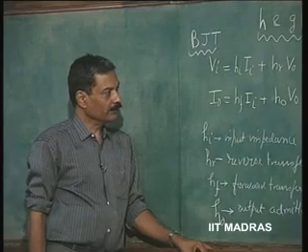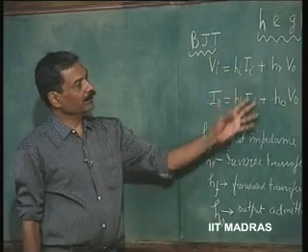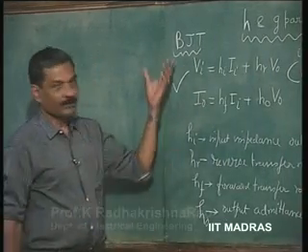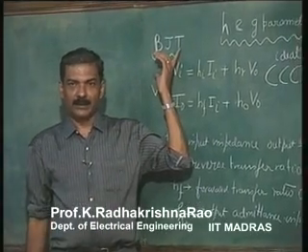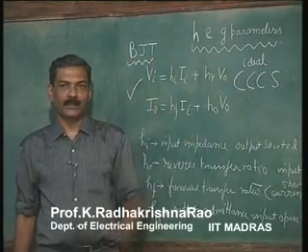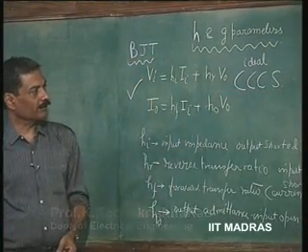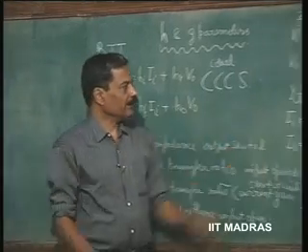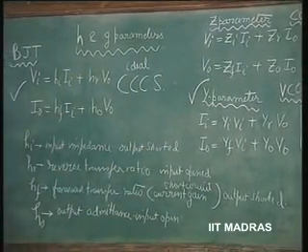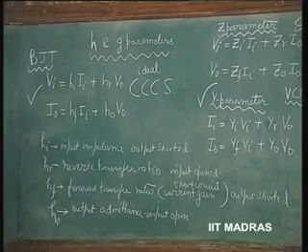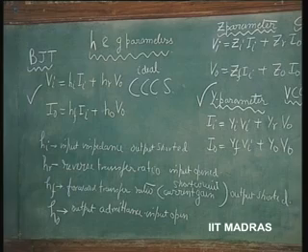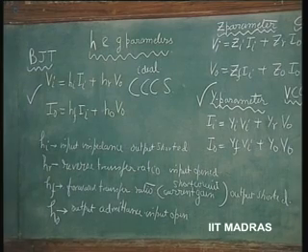So, this parameter is quite a useful parameter because of its close association with a device, okay, which is closely linked to the ideal source that it is trying to simulate. And other parameter which is also very useful parameter which is measured, okay, normally for any device is Y parameter, primarily because these are all short circuit parameters easily measured.